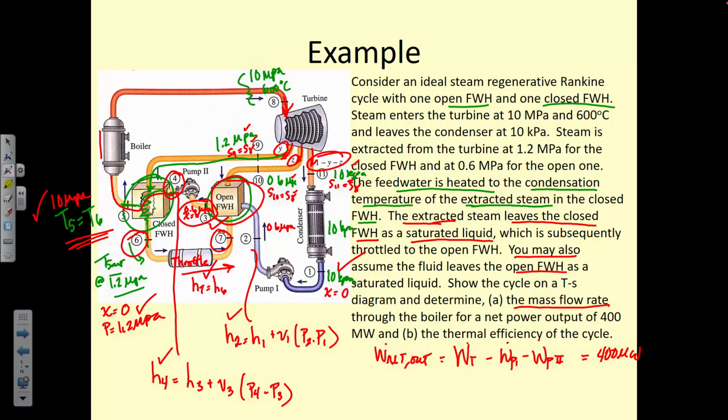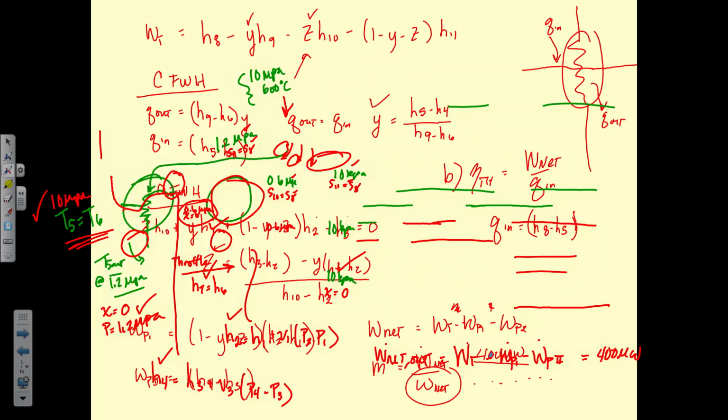Yeah, so the temperatures that are in table A6 for the superheated region are just telling you what the saturation temperature is for that pressure. So if you get to that temperature, you're no longer superheated vapor. Right. So it should match the tables. And if it doesn't match, it's an error.